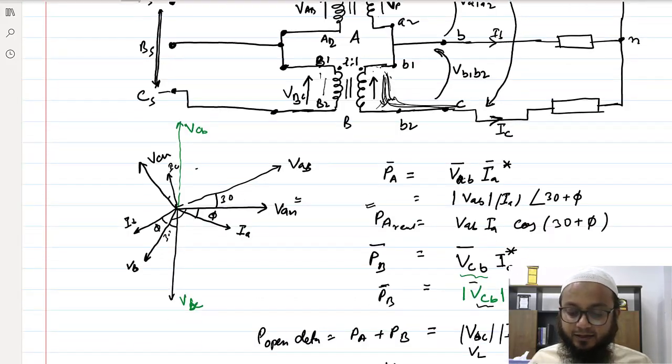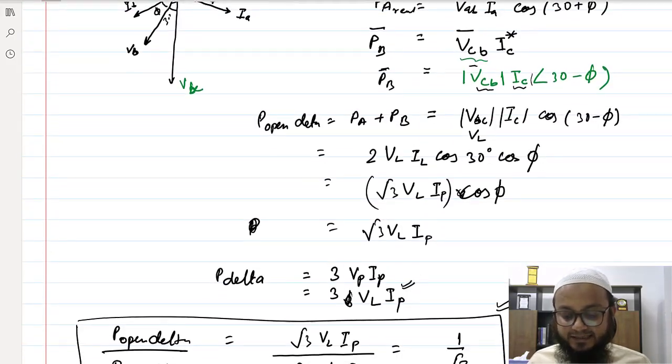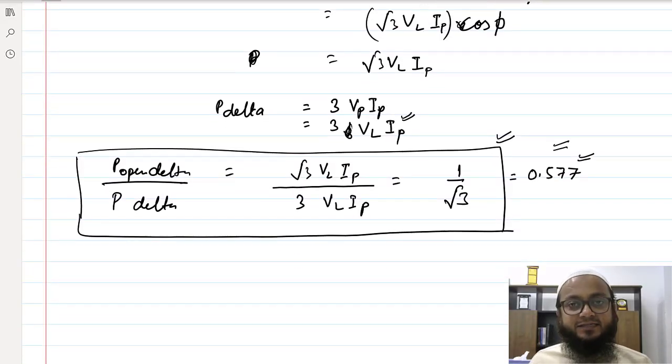In some places earlier they were getting 3-phase supply using just 2 single phase transformers, and they were getting a balanced 3-phase supply as well. And this is one advantage: let's say I'm using 3 units of single phase transformer to make a 3-phase supply and 1 phase goes out, we can still operate it, but at a reduced power.